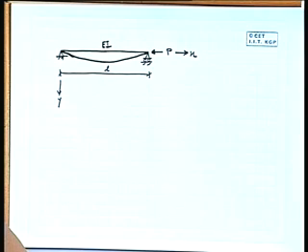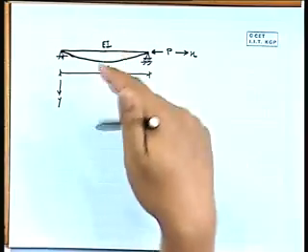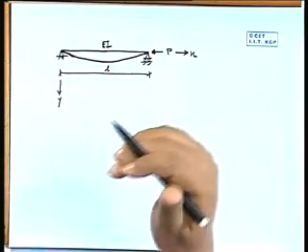Now, when will we get bending? When P is below P critical, bending will not be there because there is no transverse load. So it should be either at the critical condition or above. Say the critical part we are interested in; above it will not be stable, right.